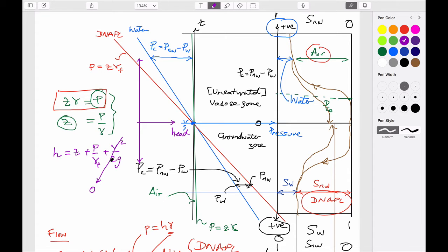All this term really represents is that if you take a mass of fluid and accelerate it at some velocity, that change in velocity has to act against inertia. And so this is only important when flows are high enough that the changes in velocities are large enough to have a significant part of inertia in the system. But if the absolute velocity is tiny, then by definition the change in velocity can only be tiny, and therefore we don't have to worry about this term. And so we're left only with these two remaining terms.